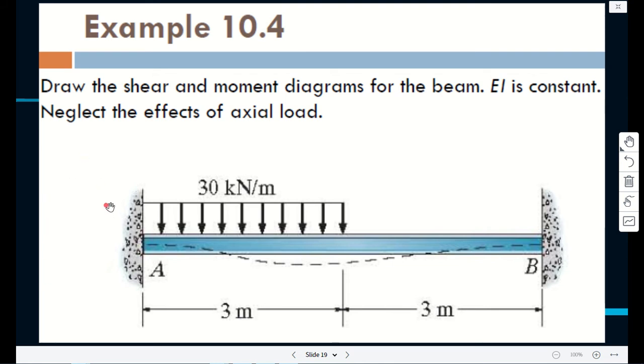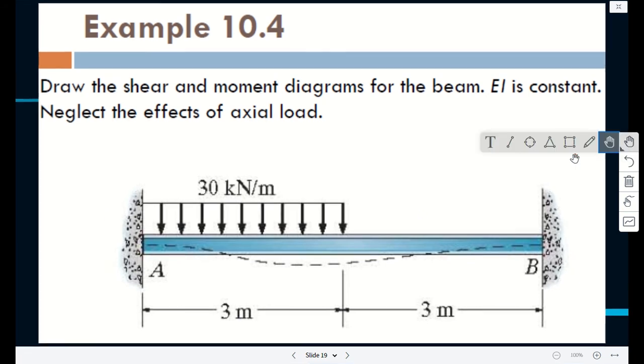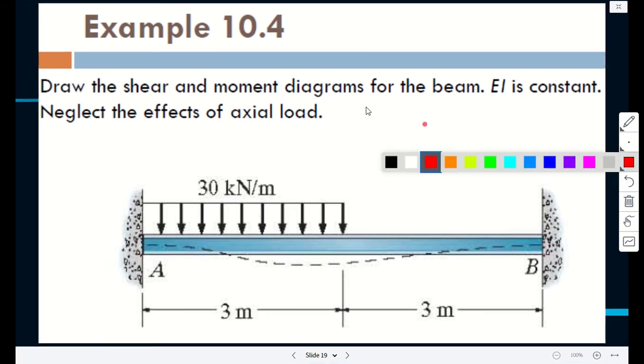Sorry, I lost you. Find the what? Reactions at A and B. Are you sure you can do that? Yeah, when you have the distance and the UDL, you can take moments to one side, say at point A, then calculate the reaction at B, then use the sum of forces, upward forces, downward force, then you find the reactions at the other end.